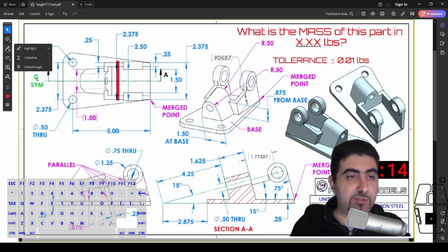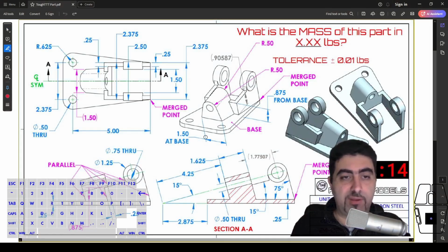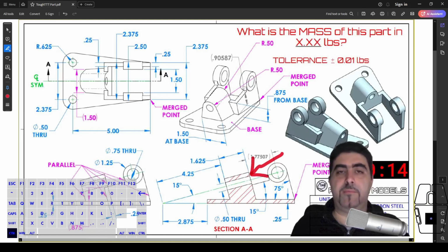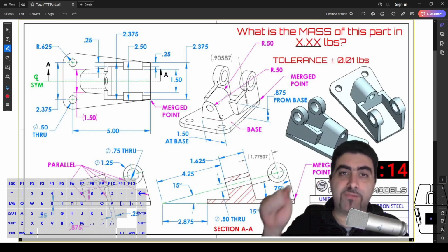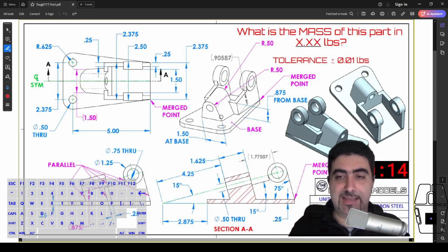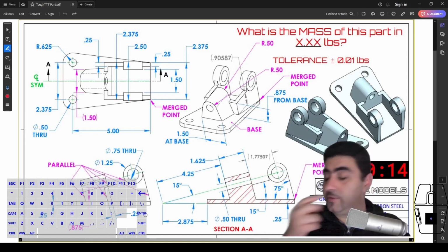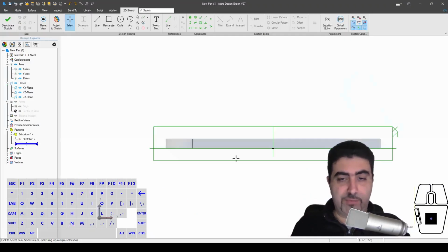Oh, sorry for that. So what I'm going to do is extrude it up there, and then I'm going to extrude cut the tombstone shape by sketching on this plane that will be created, right? And that way I will have an edge down here which I can project. And I can mark that 1.5 inches straight on that projected line and get what I want. It's going to be a bit of an involved way to do it, so bear with me.